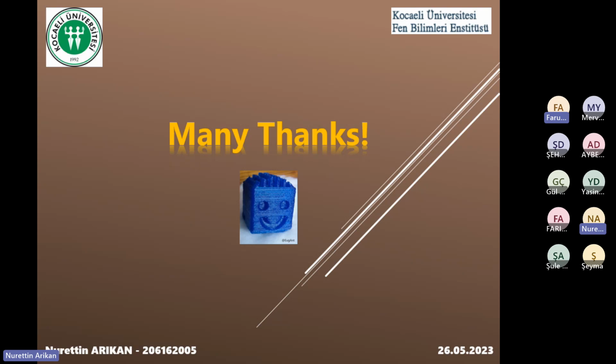Since it's a semi-crystalline polymer, it has advantages in this sense, because for an amorphous or 100% crystalline material it would perhaps be difficult to alter the properties, but here it's possible to alter the parameters and find an optimum temperature range under the Curie temperature in order to increase the beta phase in the microstructure so that the PVDF will be piezoelectric PVDF.